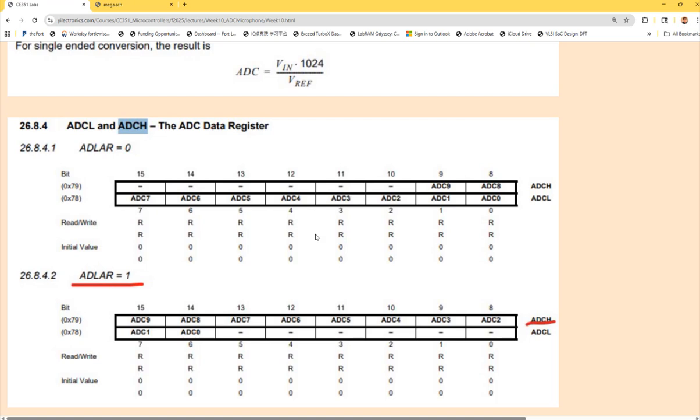See, these upper 6 bits are not used. So I have 2 bits. I mean, more bits will be more resolution. It's more helpful, more information. However, it's an 8-bit microcontroller system, so all the registers are 8 bits. If you want to hold another extra 2 bits, you need a different register. That's why it's using 2 registers to hold the 10 bits, right?